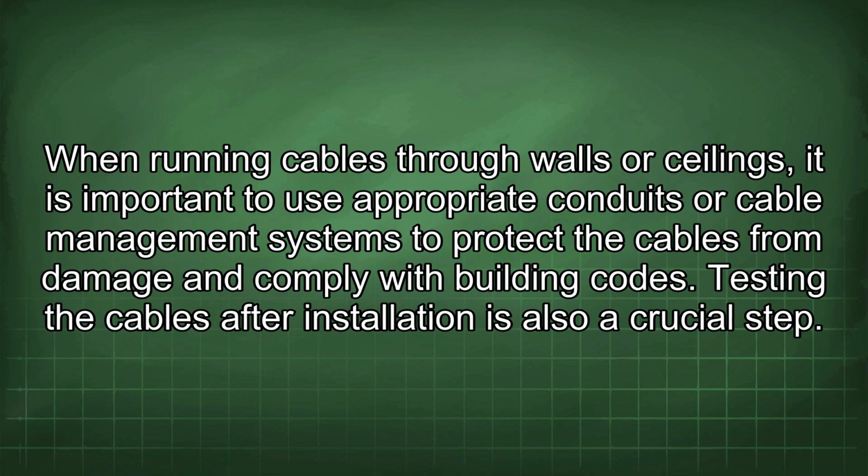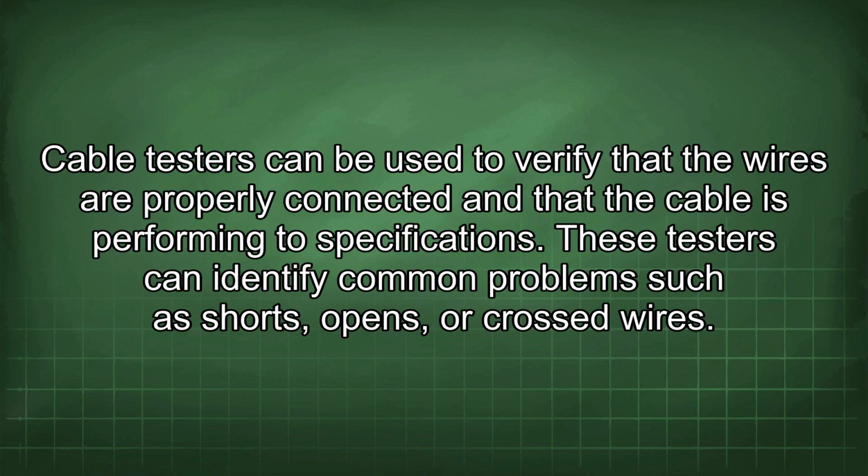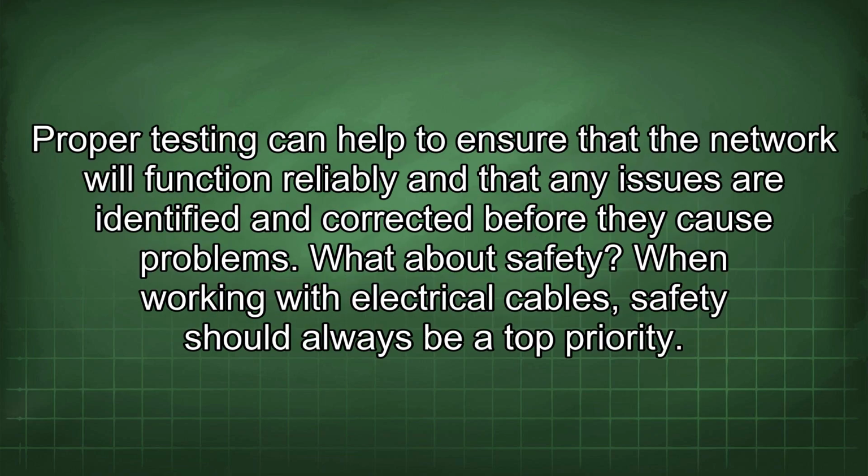Testing the cables after installation is also a crucial step. Cable testers can be used to verify that the wires are properly connected and that the cable is performing to specifications. These testers can identify common problems such as shorts, opens, or cross wires. Proper testing can help to ensure that the network will function reliably and that any issues are identified and corrected before they cause problems.